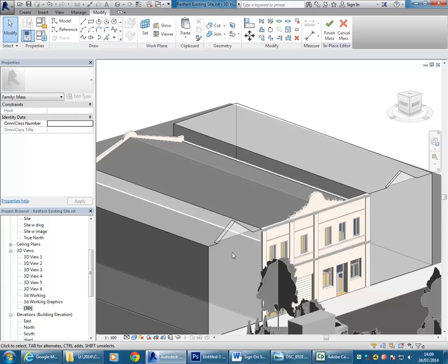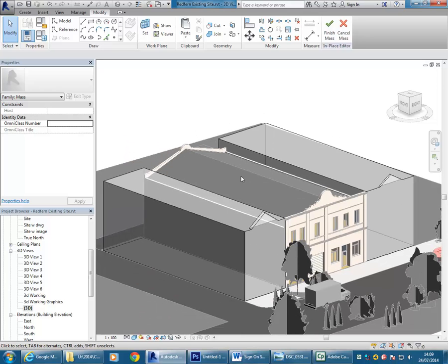Well, that's actually going flat, so you've got to get it from the front. So just click on the line button. That one. Yeah, and then go to that one. Draw on Face, and then start on the actual surface, so it knows where you are. Yep, that's it. See how it's highlighting that surface, and then you get the angle. Yep, no worries. So yeah, or 35, I think it was in the end. But whatever looks good to you, doesn't really matter.